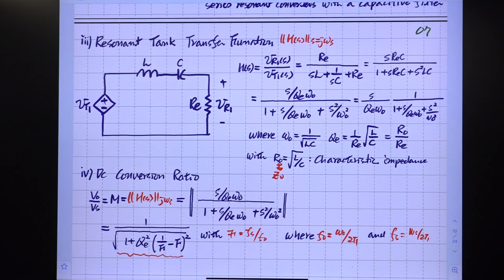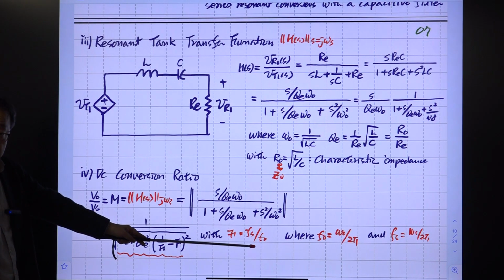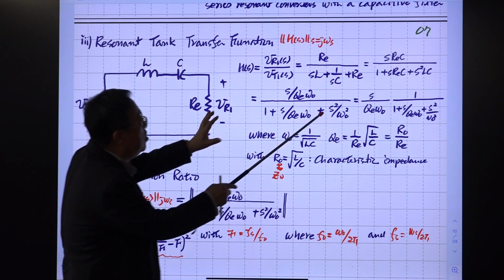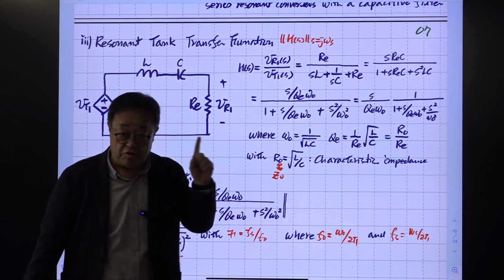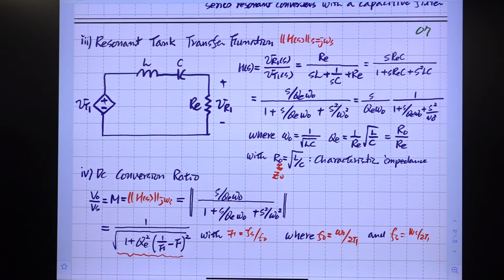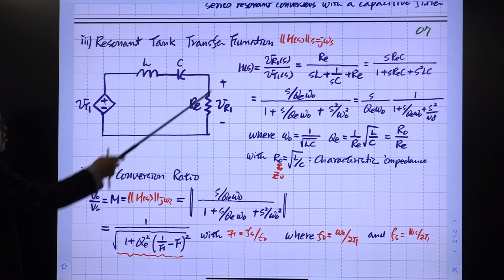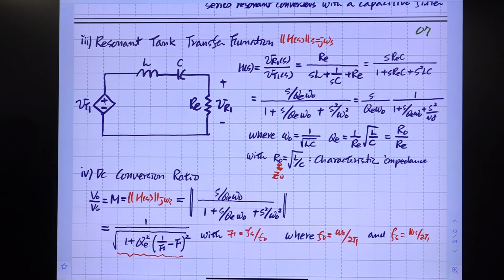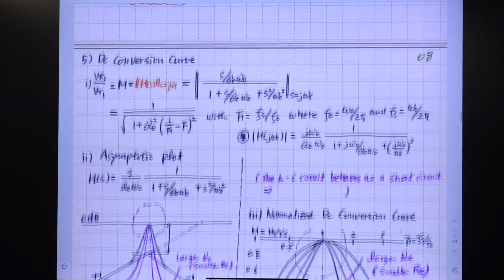Okay? Put one here. That means the switching frequency is the same as the resonant frequency. Then this term becomes 0. Gain is 1. You went through this. Right? Otherwise, you put j omega here, then everything will cancel. It will just become 1. That is the stupid way of understanding this. Just watch this. At the resonant frequency, they cancel. Then this voltage is the same as this. Obviously, the voltage gain at the resonant frequency is 1. That is the maximum gain you can achieve with this series resonant converter.